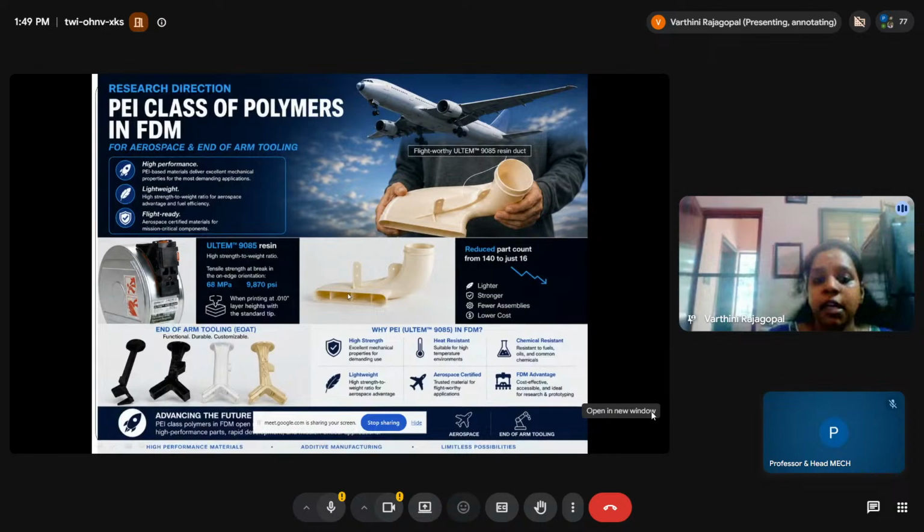So we have imported that particular data, and now we have taken that into the CAD model. So we need to build an implant that fills this region, right? So we took up 4 different structures. We have unit cells, right? We had gyroid cells, a hexagon profile, and a triangular profile. We had the 4 different lattice structures. So we tried building 4 different lattice structures, and we checked the numerical results, to see which lattice structure had better mechanical strength and stiffness as compared to the bone structure.